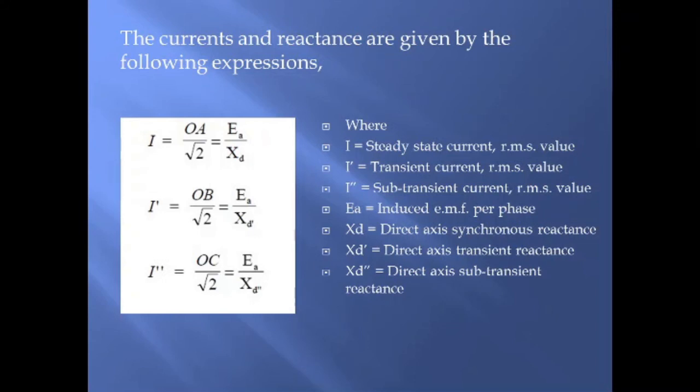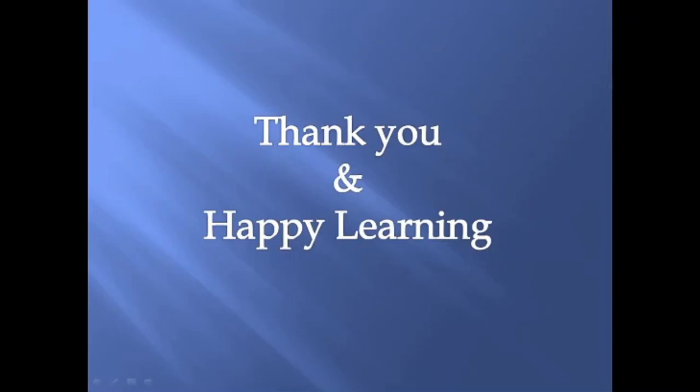I hope this thing is clear to you. I hope the concept of transient, subtransient, and steady state is clear to you. If you have any doubt till this point, just let me know. This is all about the subtransient, transient, and steady state period of alternator. So in today's class, we have seen how the alternator reacts to a short circuit or fault condition with the understanding of subtransient, transient, and steady state period.